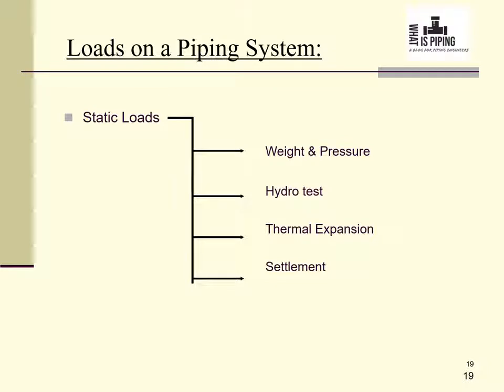So this is also a kind of static load. Then thermal expansion due to change in temperature, and settlement. Sometimes due to heavy weight, soil may settle down, normally for tank and other big size equipments, settlement occurs. So all these are static loads.